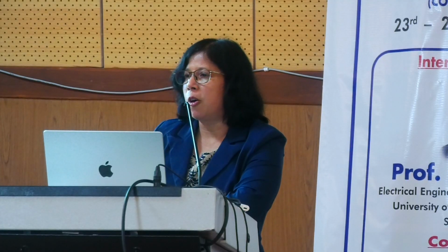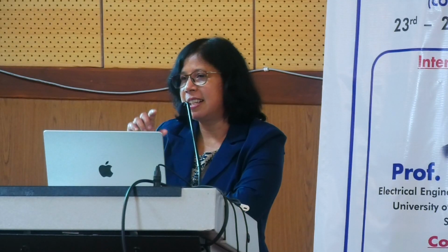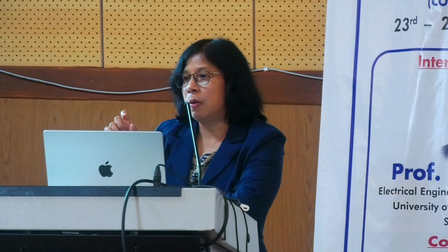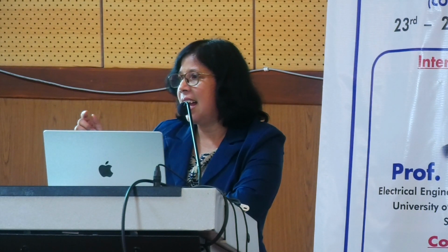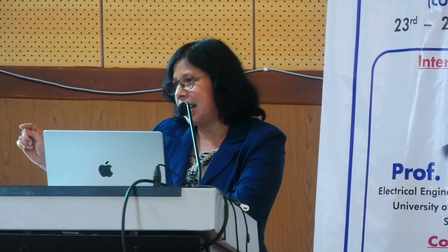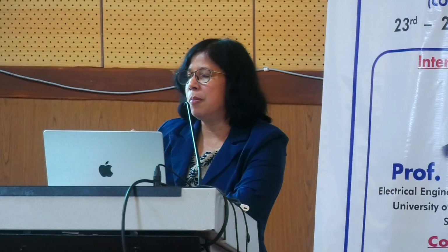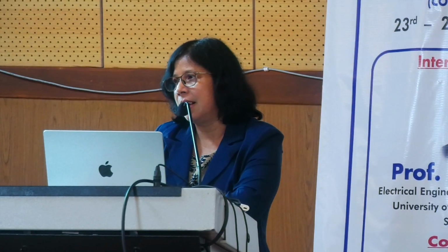For BLDC, this is the rotor they use, and the stator could have concentrated type windings, and they usually produce trapezoidal back EMF. Mostly the control of BLDC and PMSM is different. In PMSM, you will use a more advanced control like field-oriented control, but in BLDC, it is usually a much simpler control.